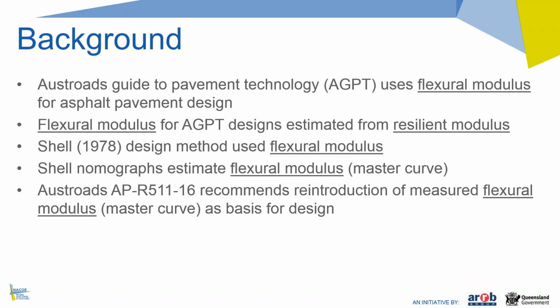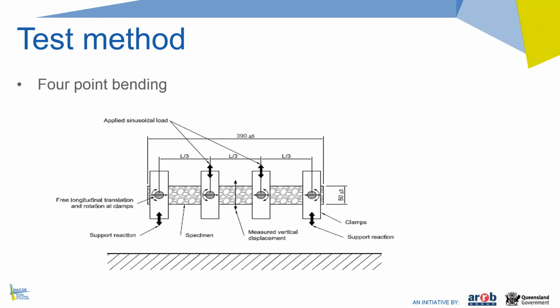So for all these reasons, a recently completed Austroads study, and the APR 511-16, that's the final Austroads report to come out of that, actually recommended the reintroduction of the measured flexural modulus and the master curve as the basis for design. So that's basically what this work brings into the TMR tech note.